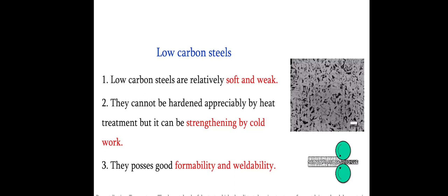Plain carbon steels are those in which carbon is the alloying element that essentially controls the properties of the alloy, and in which the amount of manganese cannot exceed 1.65%, and the copper and silicon content each must be less than 0.6%. This plain carbon steel has different names. Other names are carbon steel, non-alloy steel, and straight carbon steel.